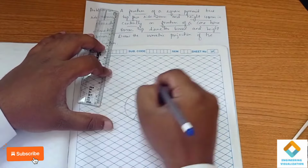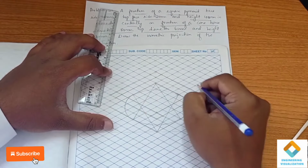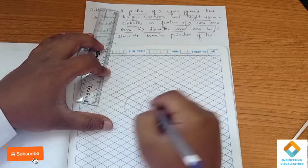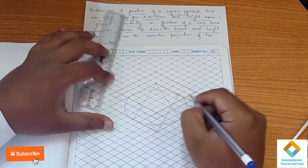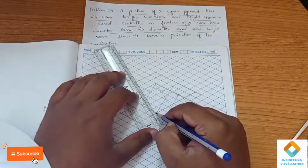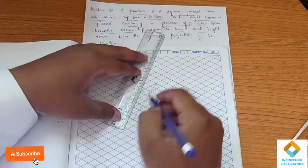Just I am marking the corner points of the box. Again, four arc by center method. Mark the middle point of the box. So here it is 60, which means mark exactly the 3rd box. So again four arc by center method to construct the ellipse here.